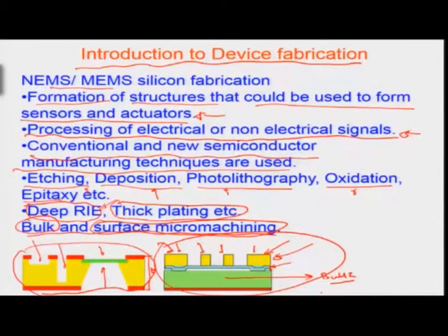If I look at such structures and how they are formulated, this structure right here can be formulated through etching. There is a process called etching. Etching can be a high aspect ratio etching, which is usually done using gas plasmas. This structure here is a high aspect ratio etching. This is a low aspect ratio etching, but this can be done in a wet chemical stage with wet chemistry processes.